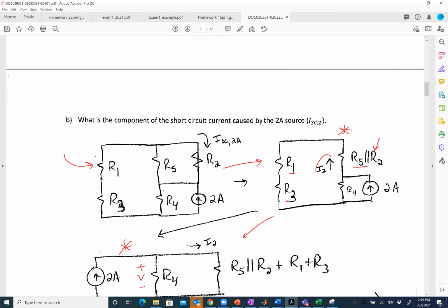How are their voltages the same? If I look at here, and do a KVL around that loop, and I call this Vx and call this Vy, I'll see 0 equals minus Vx plus Vy, or Vx equals Vy. KVL and KCL are basically the guide path for everything we do. All of electrical engineering is guided by those 2 statements plus Ohm's law. That's all it is. The rest is just fluff.